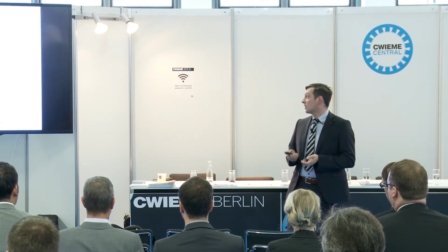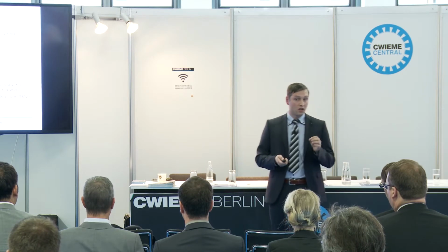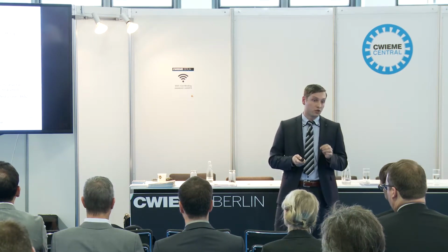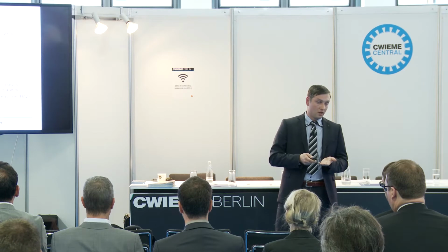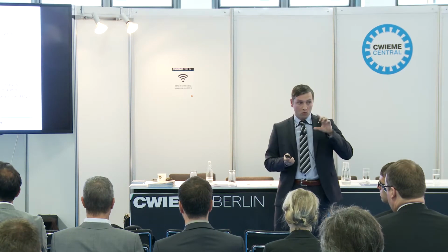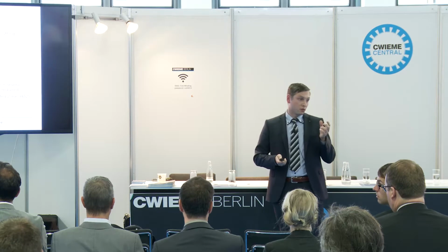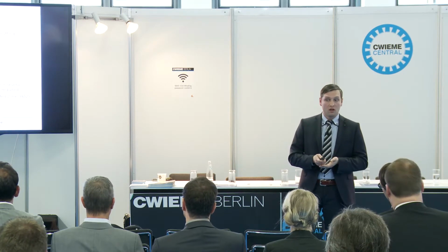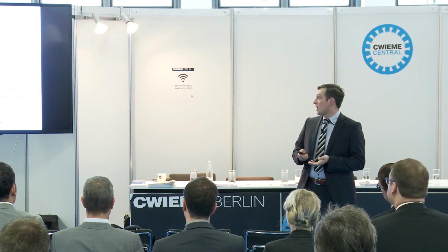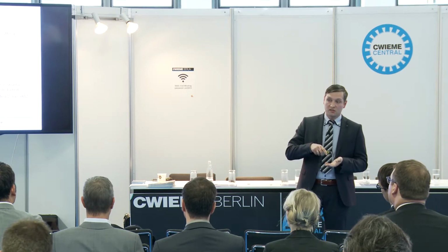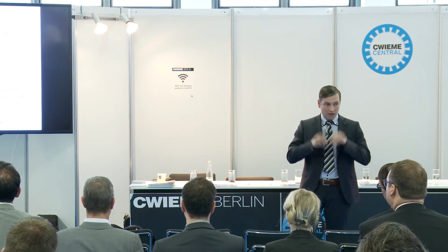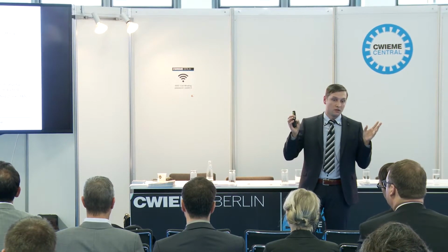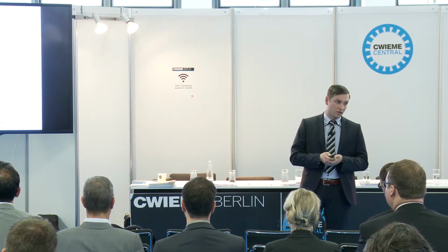On the contrary, laser remote cutting utilizes another process principle. The idea here is to vaporize the material with as little melting as possible. Here we don't melt the whole volume, just, let's say, between 5 and 15% of the thickness. The laser beam creates high pressure in the molten area with vapor that expels the molten material from the cut curve.